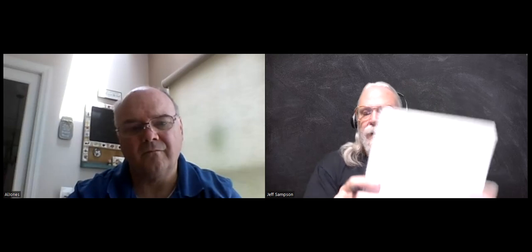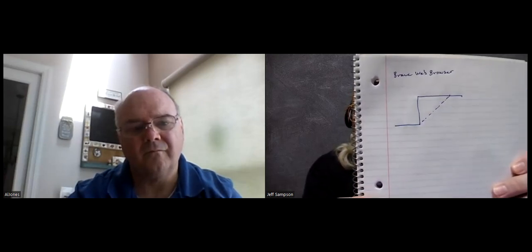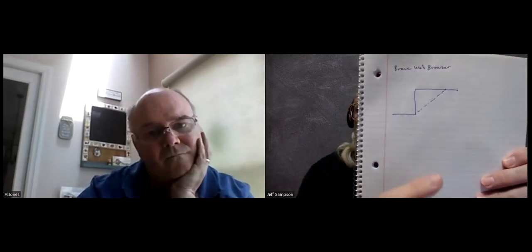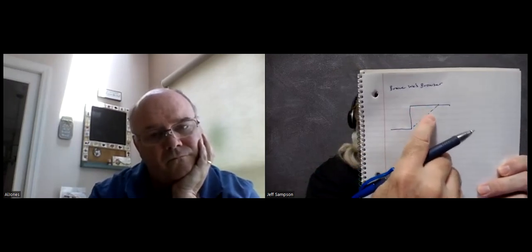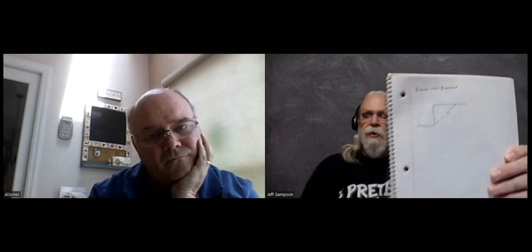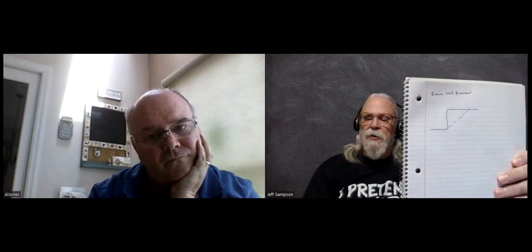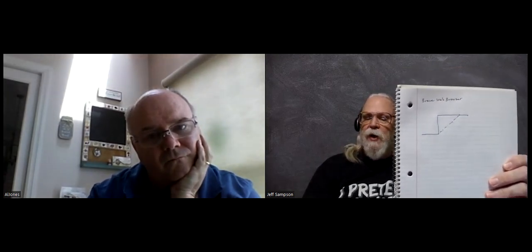So basically, this is going to show up. You give it a step function like that, and then by putting this extra code in your loop, it's going to move the target angle that your PID is trying to follow. And this is backwards here. Anyway, you can control the slope of that, and you can slow it down so it's not trying to move at full speed to get out to the location you give it.